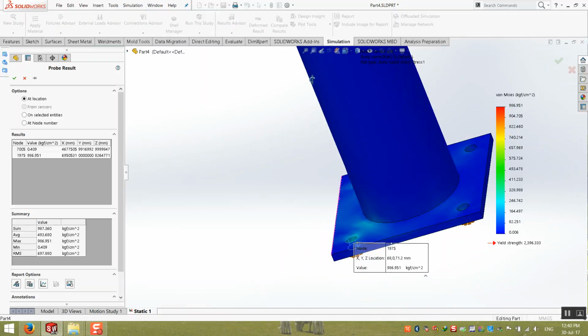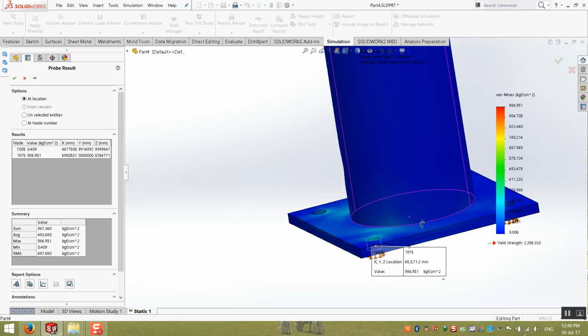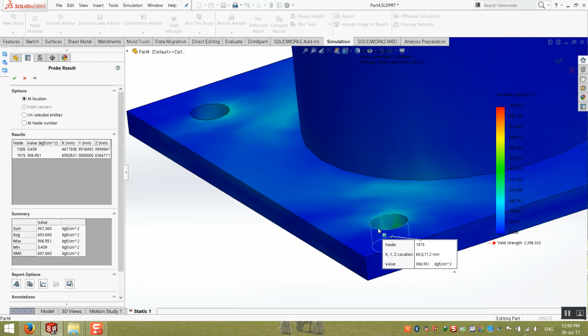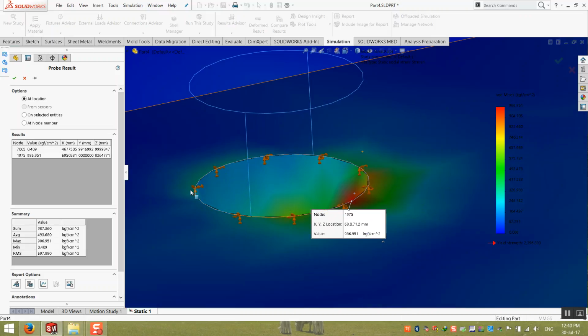In the direction of load. Why? Because here you make tension like that. Tension, the screws need to pull up from the floor. Okay, so you have the maximum resistance here, and this number is very important.